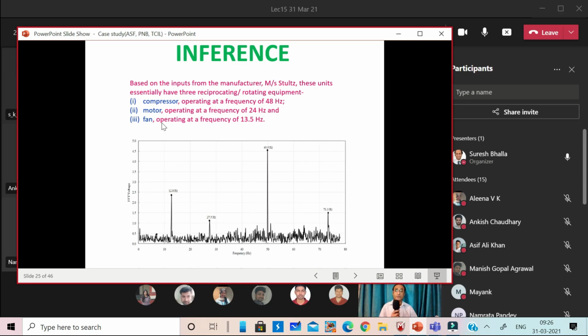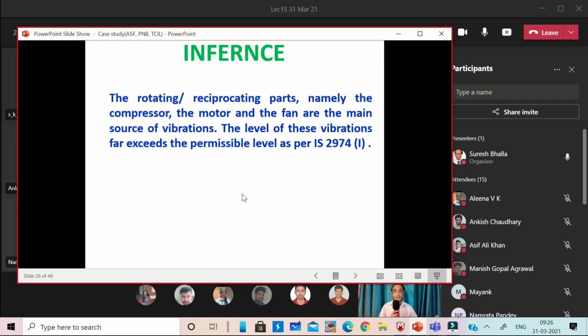It was also found that these machines were quite old, and then we requested immediate servicing, and we also proposed that we will design the paddings, and that the machines should not be rested directly on the steel frames which are directly connected to the floor slab.